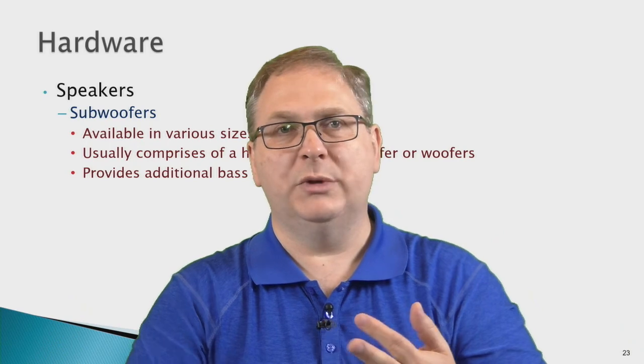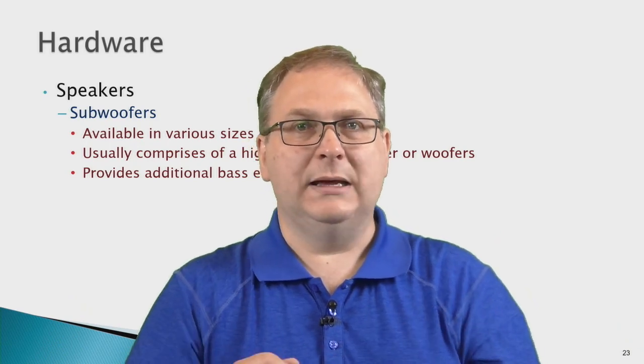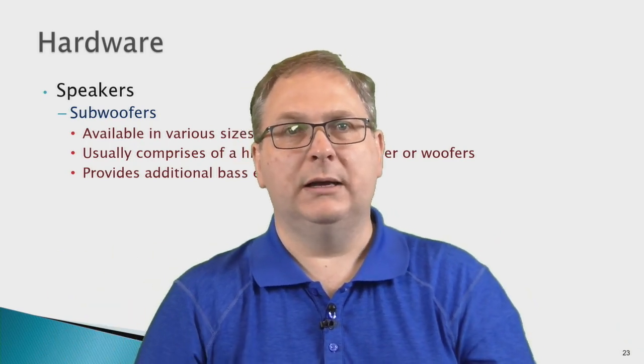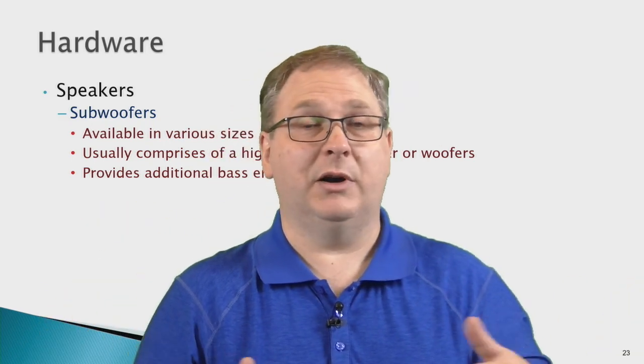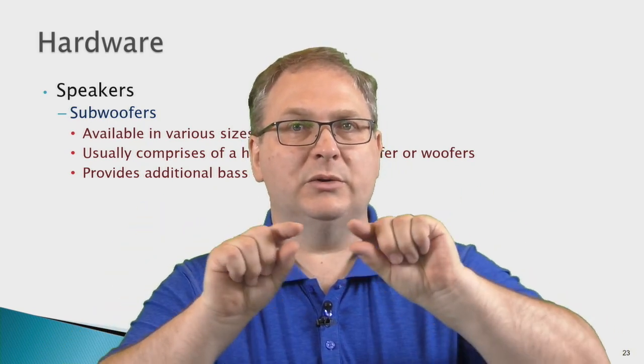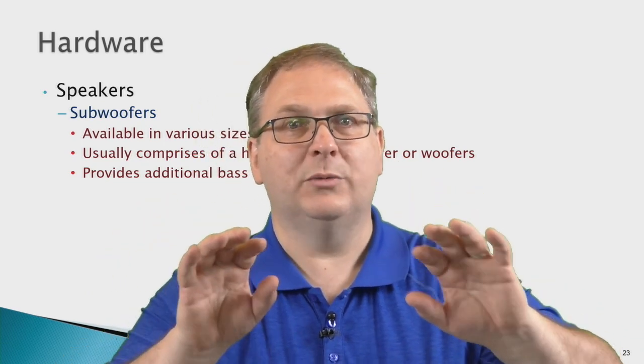That can affect your low mids, it can affect your high frequencies as well, and it can actually sound like distortion. So in other words, the speaker itself is distorting, maybe not the amplifier, maybe not the mixer, depending on how much output you're putting on it. So it's good to separate those signals, let the speakers do what they've been designed to do, let the subwoofers do what they were designed to do.